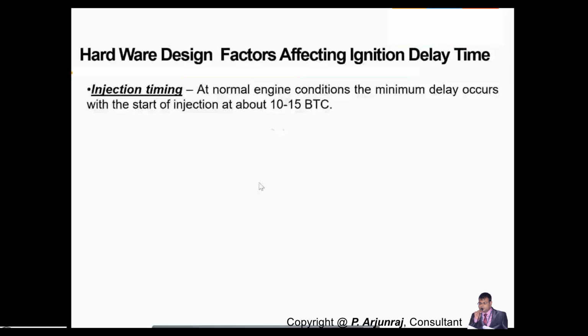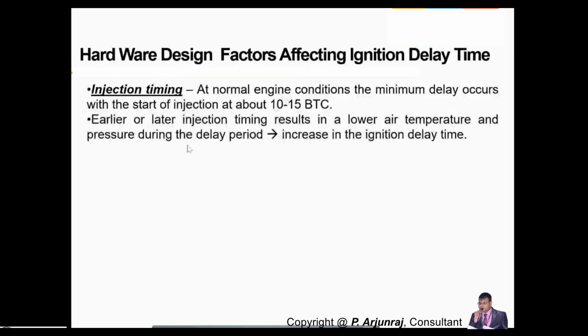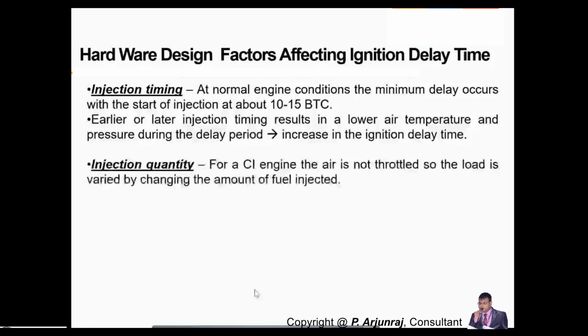If you start injecting the fuel earlier than this, it may increase the ignition delay time, and may also result in a high ignition delay period.